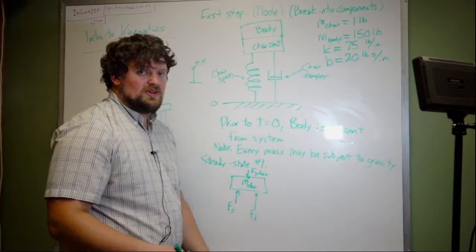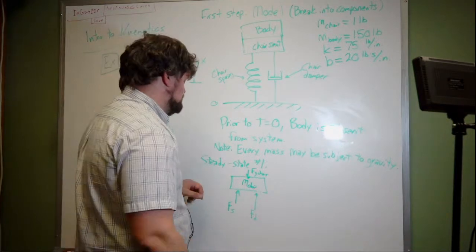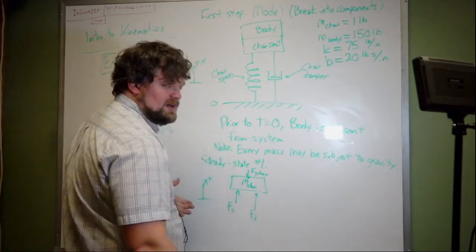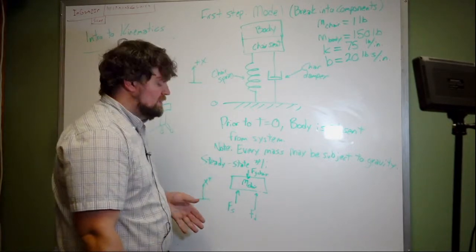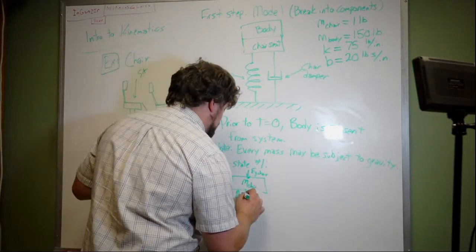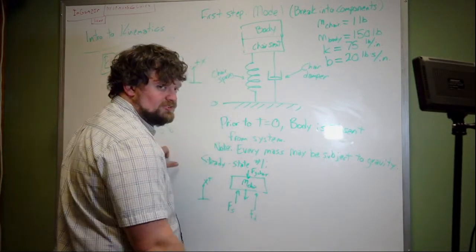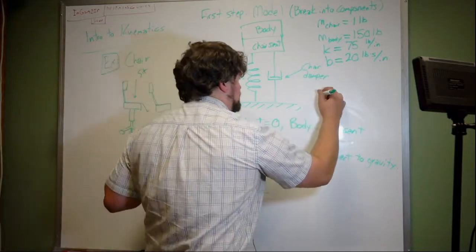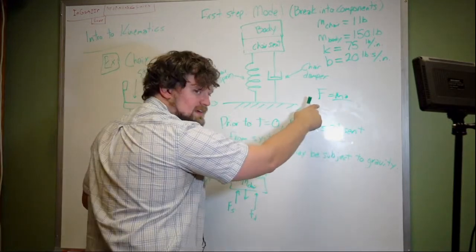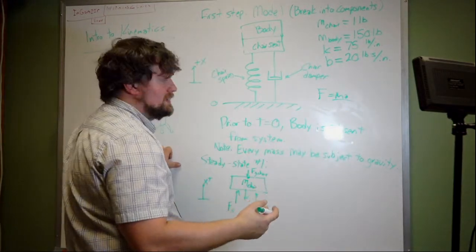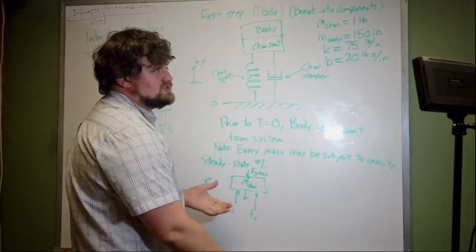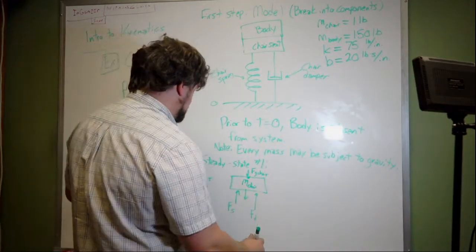Okay, and then we'll also have an inertial force. Typically for an inertial force, we're establishing X positive in the upward direction. What you'll do is make the inertial force always point in the negative direction. Do not ask me why, but that's how you end up with your F equals ma, because this inertial force is a negative over here, and it's always a negative. So you pull it out, move it to the other side, and have it be a positive. It's just always considered negative, okay?